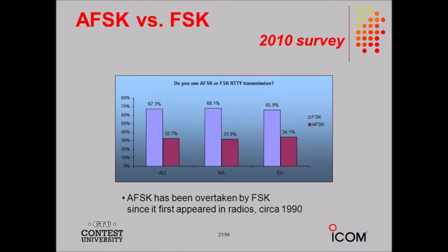We can imagine this circuit as an RF amplifier for the carrier with the instantaneous gain dependent on the instantaneous audio input amplitude. We can also think of the circuit as a mixer that combines the RF carrier and audio signals to produce sum and difference signals above and below the carrier frequency.